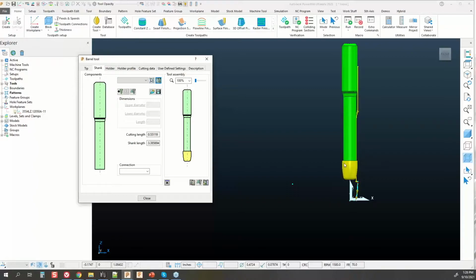That can be important later on as we may be reaching down inside of a cut and we need to have that extended and shank reliefed area for clearance on our tool. So again, that's an important part to think about when we get into looking at toolpaths. I'll start to show where I'm looking at the successful type of cutter I might try to choose here, as well as reach, rigidity, all that stuff comes into play.